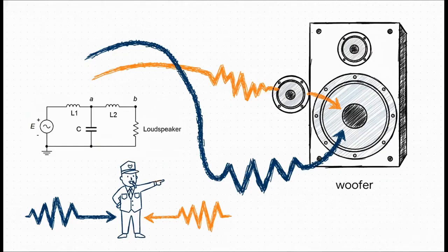And here's the magic, right inside the speaker. It's a circuit called a crossover, and what it does is brilliant. It uses an inductor, which, remember, resists high frequencies more, to send all the low-frequency bass sounds to the big woofer, and it uses a capacitor, which resists low frequencies, to send all the high-frequency treble sounds to the little tweeter. It's basically a traffic cop for frequencies, directing everything to exactly where it needs to go.